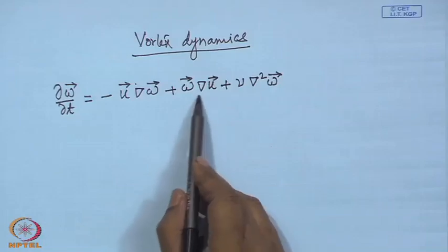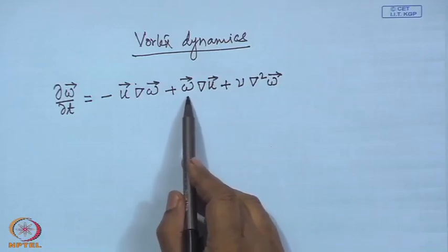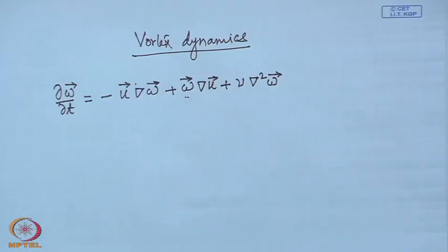The second term, as we described at that time, is rotation and stretching of the material vortex element. We also said that this effect is a secondary effect; it simply redistributes the vorticity locally. It does not change the broad feature of vorticity distribution over the entire fluid.